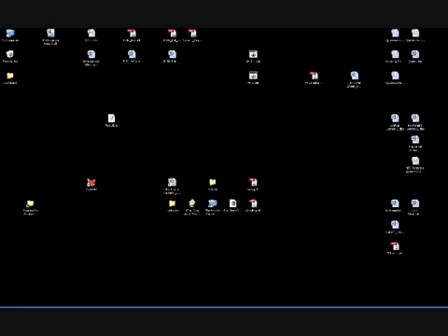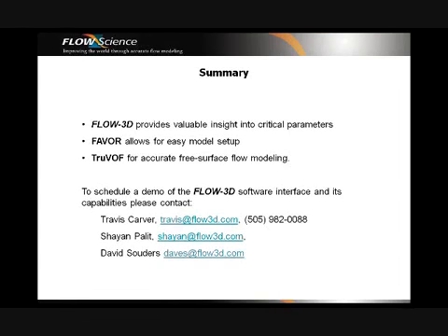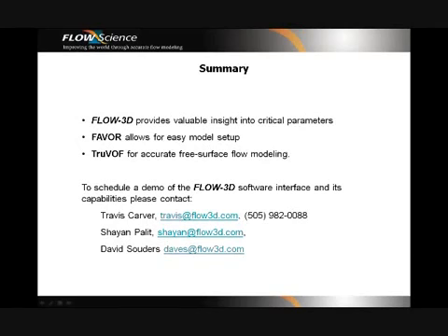Another question, how is turbulence modeled in Flow3D? Well, in Flow3D we've implemented 5 different models. We have Prandtl mixing length, 1 equation, 2 equation K-epsilon and RNG models, and then a large eddy simulation model. Our formulation includes the influence of fractional areas and volumes, the FAVOR method, and that generalizes the turbulent production or decay associated with buoyancy forces.